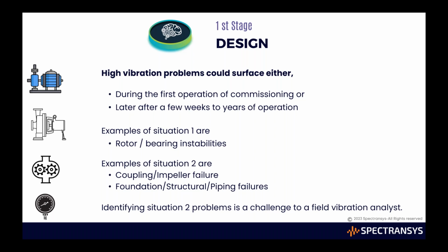Then some other design related problems may surface after a long time, related to coupling design problems or impeller design problems, or inadequate foundation designs, or the structural and piping. Those are the things where failures can occur over a period of time, resulting from inadequacy in the design concept. Identifying the situation two problems, meaning after the design stage, on machines that have run for quite some time, is a challenge to the vibration analyst. It's not so easy for us to analyze with the tools and the knowledge which we have.